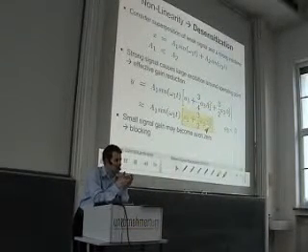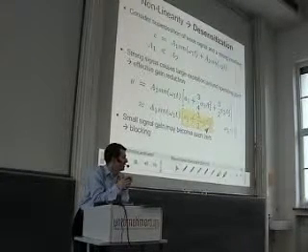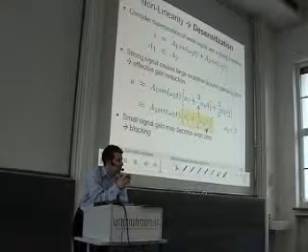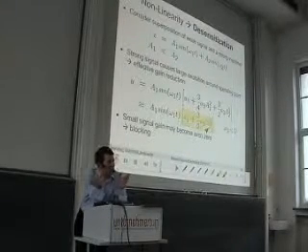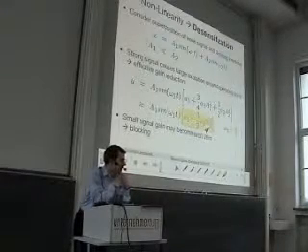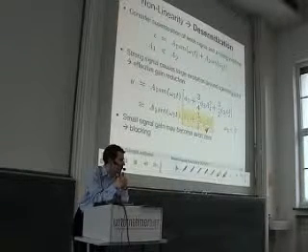So at the beginning the second signal has nothing to do with the first one. And in a linear system this would always be separated from the first one because it's at another frequency. But now we see that due to the nonlinearity, the amplitude of the second signal reduces the gain that the first signal sees through this system.